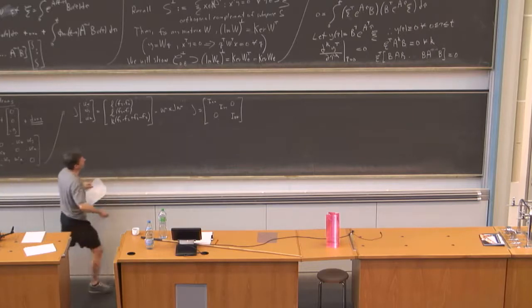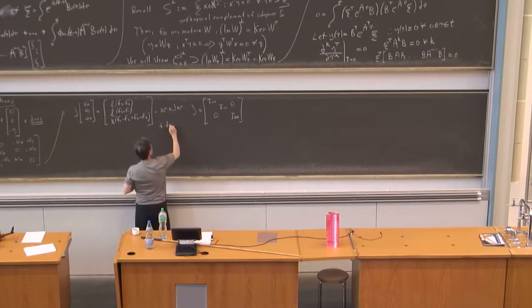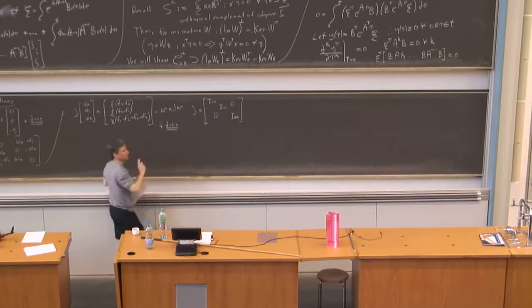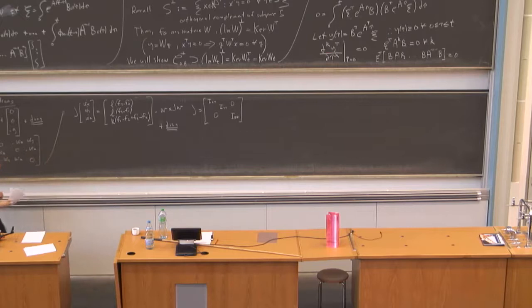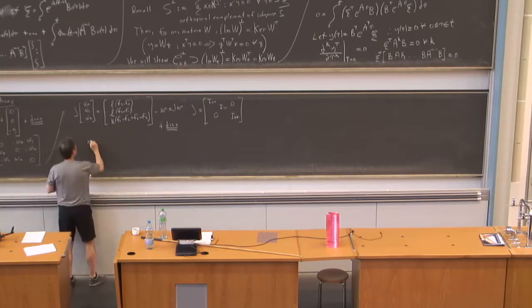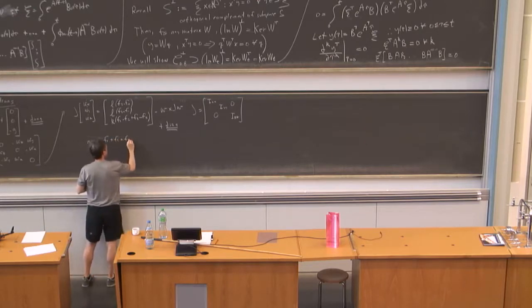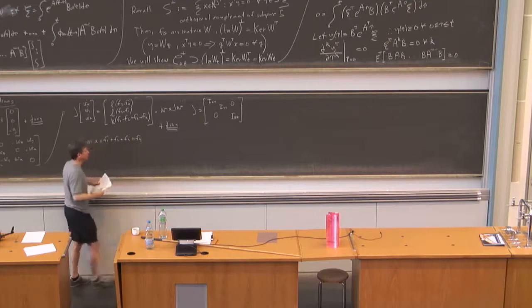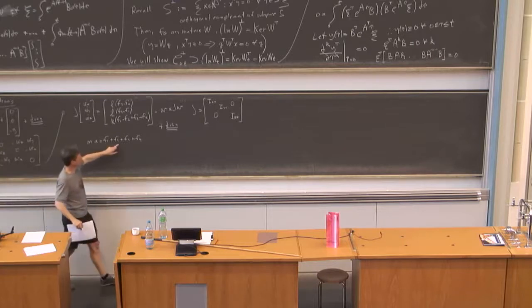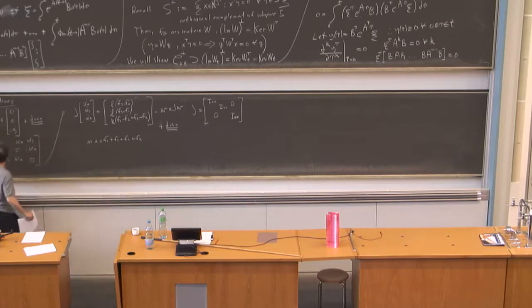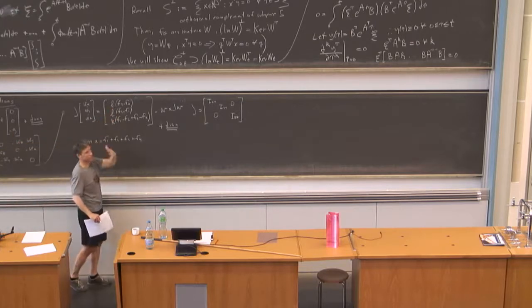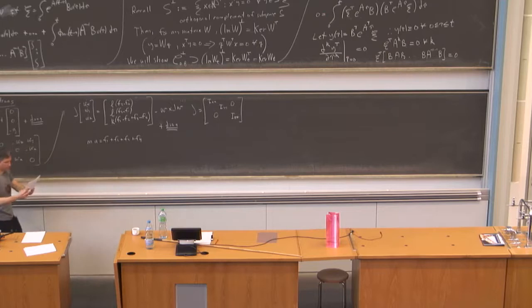Plus, there's a drag term, which I'm going to omit for now, but I will need it later on. And the last thing that I need to write down is that ma is equal to F1 plus F2 plus F3 plus F4. That's this a term here. So you can see how these 4 thrusts allow me to produce a net thrust in translation and allow me to apply moments to change the orientation of the device.